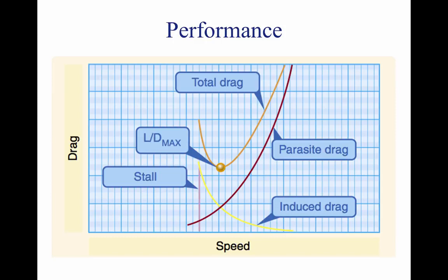For the aircraft to remain in steady, level flight, equilibrium must be obtained by a lift equal to the aircraft weight and a power plant thrust equal to the aircraft drag. Thus, the aircraft drag defines the thrust required to maintain steady level flight. As presented in Chapter 4, Aerodynamics of Flight, all parts of an aircraft contribute to the drag, either induced or parasitic drag. While the parasite drag predominates at high speed, induced drag predominates at low speed.